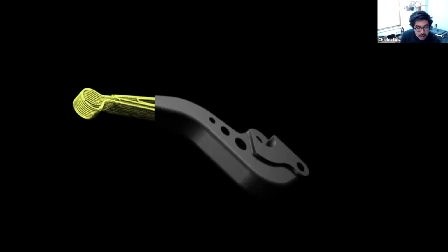Rob says, can you print parts in contact with gasoline or oil? Yes, you sure can. Nylon is very resistant to petrochemicals, so that's totally fine. Hand calculation for stress, continuous fiber in the XY direction based on the number of walls and total height. Yeah, absolutely. Hopefully that estimate I gave you earlier, 1 millimeter per pass of fiber. So in any feature, let me see if I can go back to the slide here.